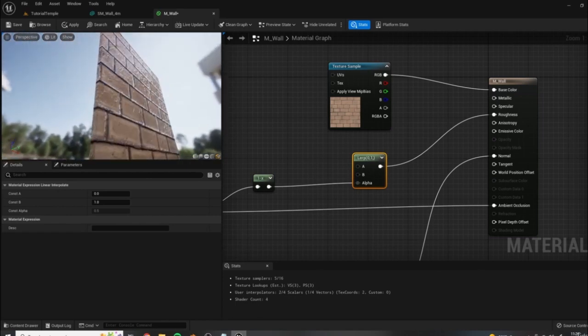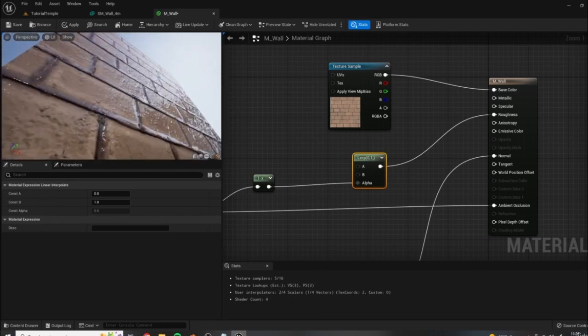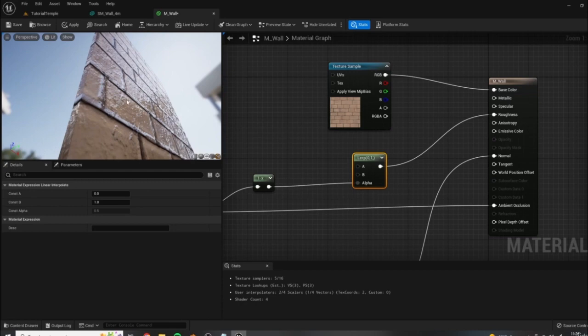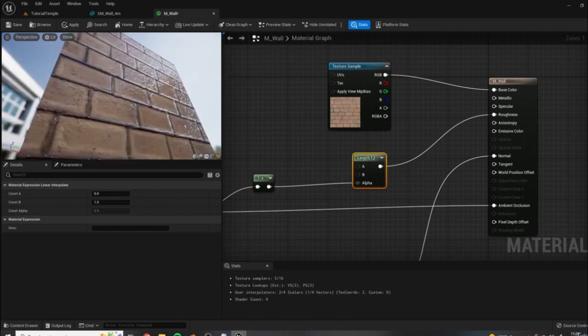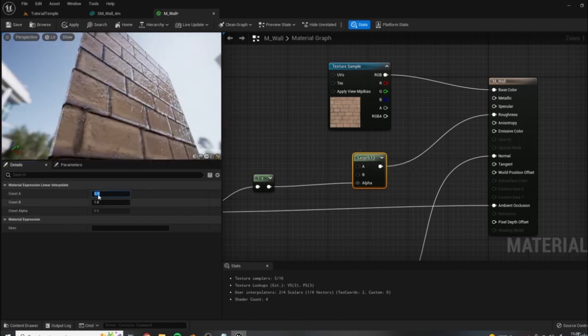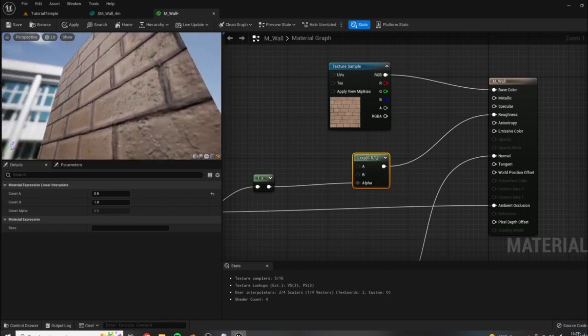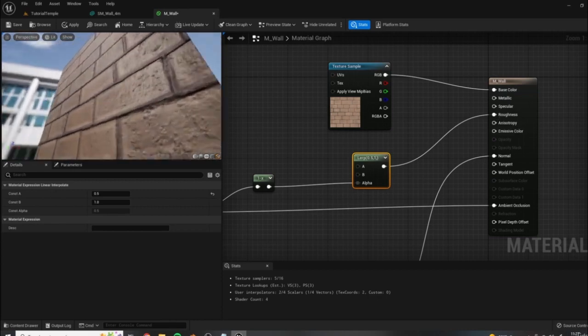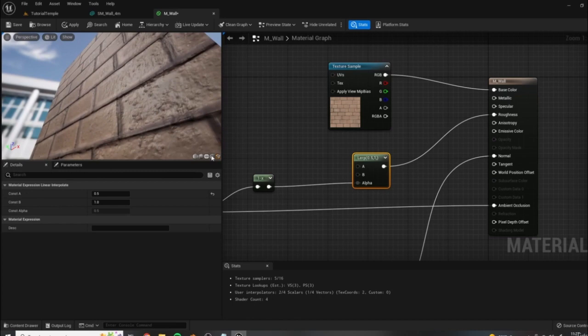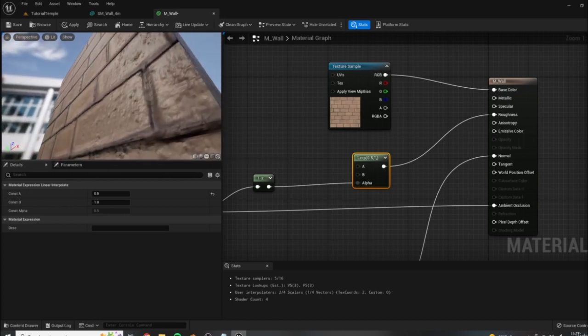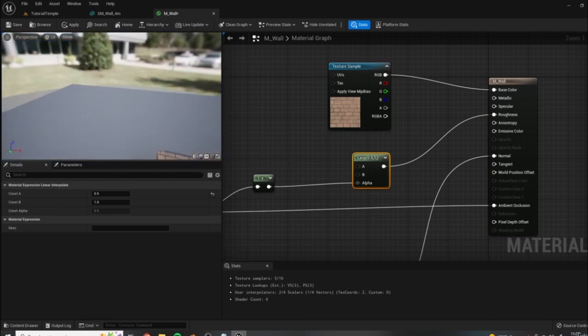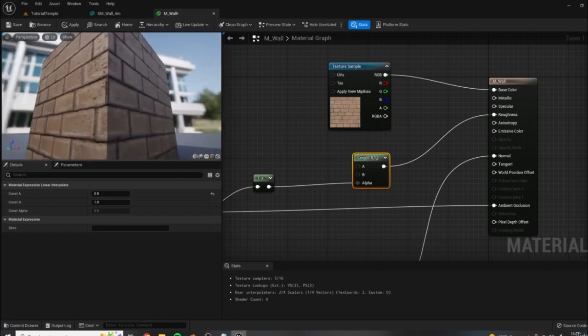So here we get a very similar result in that we have a variation between very smooth and very rough. So if I wanted this to be rougher, less shiny, all I needed to do is to up this A value to something higher. Let's try 0.5. All right, and there we go. It's a very subtle difference, but especially when you view your meshes at more of a glancing angle, it does make a lot of difference on the overall effect that these meshes have.